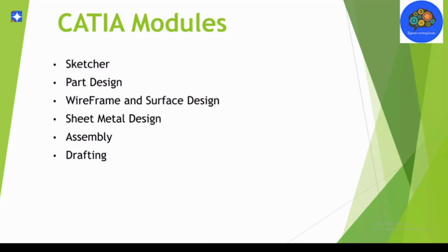Before the manufacturing of the product, 2D drafting should be done, and then those 2D drafted drawings will be sent to the production department. For manufacturing a product, documentation is a must, and that documentation must be in 2D format only. That is called a control copy. The control copy will be sent to each and every department, the officers will sign it, and then it will be sent to the manufacturing department to start the manufacturing.